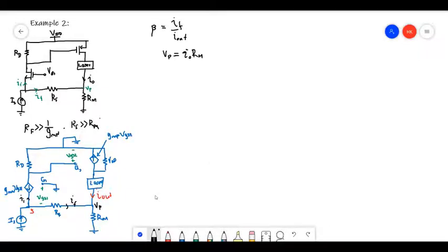And then we need to find IF. Here we are mixing in parallel. Due to this shunt mixing, the input resistance will drop. You saw in the previous calculation also that the input resistance of a current amplifier will drop by a factor of A beta.